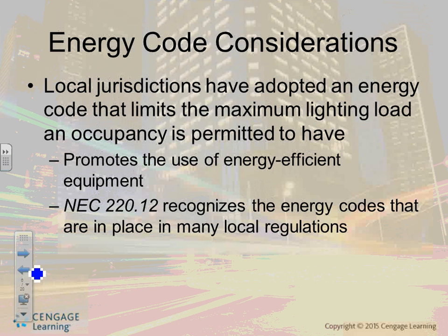Yes sir. The first thing when you do the calculation is you're going to ask yourself, what is the future planning of this building, as a designer, as an engineer? When you start your calc and meet with the customers, ask what their future planning is for this building. Are you planning on adding to the building? Are you planning on adding loads to the existing building? Are you planning to add another section to the building? You take all this into consideration when you size your service.